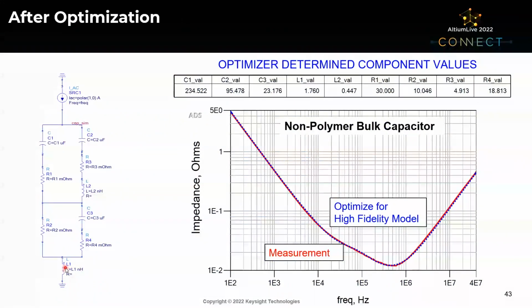Now I can turn the mounting inductance on or off. I can short this mounting inductance, pull it out if I want to connect to an EM model of the printed circuit board, or I can leave it in if I want to just do a simple SPICE simulation of the network. So that's a very powerful method here.